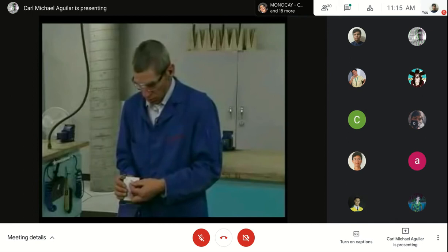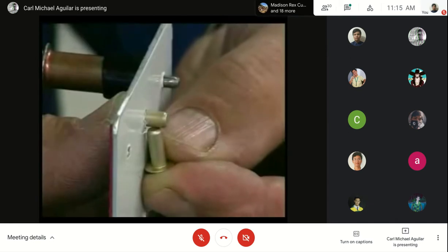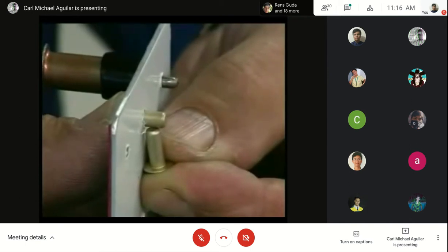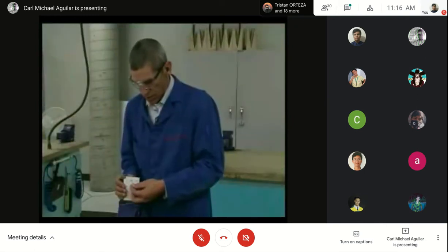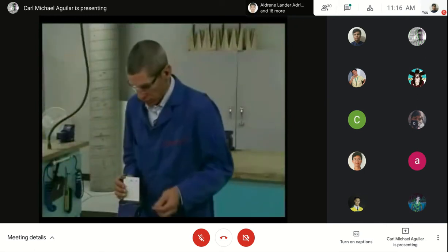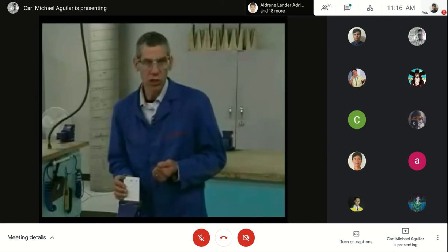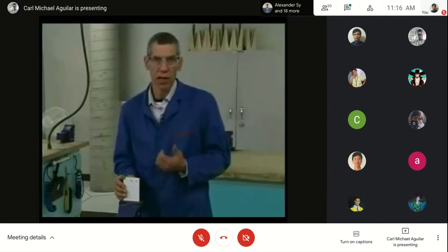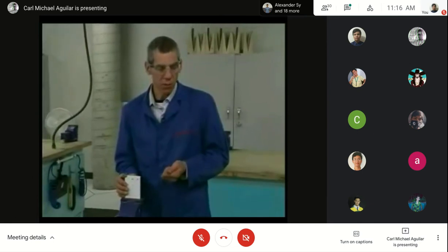Nice to have a longer rivet so you can handle it easier in your hand. Set it alongside the rivet I've stuck through and look at the back side and see that it is sticking out greater than 1 diameter, but less than 2 diameters. So it's approximately 1 1/2 diameter sticking out the back side. This will ensure that I have enough material to form the proper shop head. Now that I've selected the correct rivet length, I'll need to select the correct bucking bar.